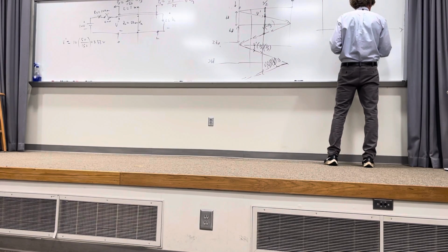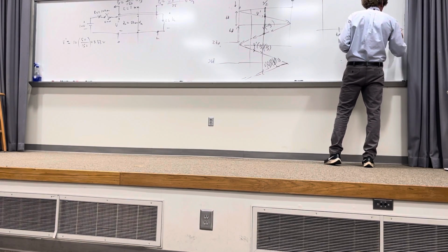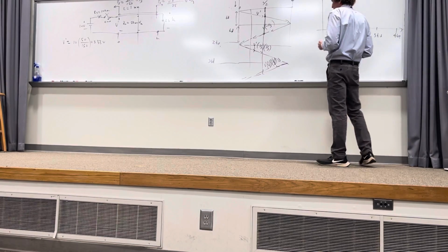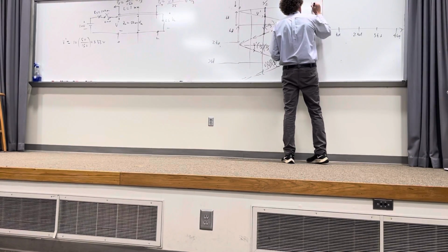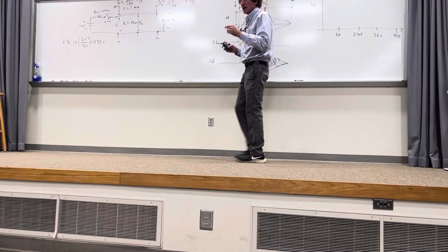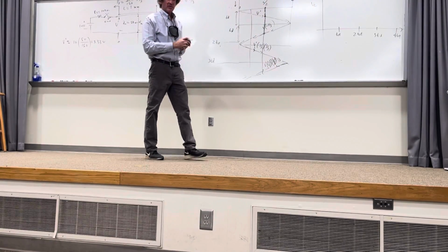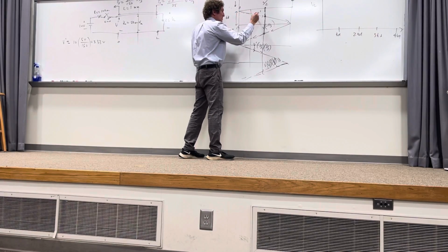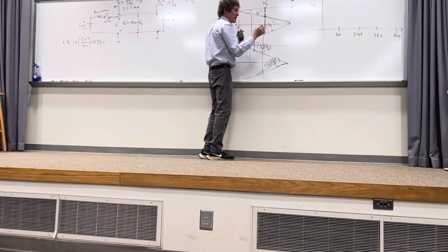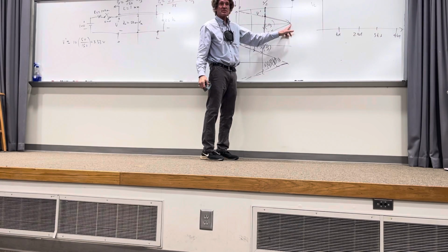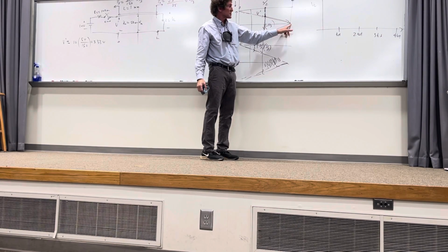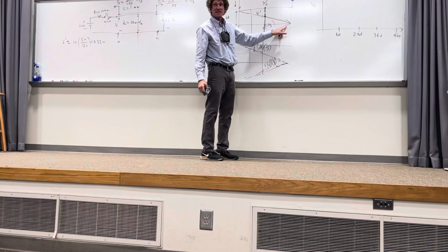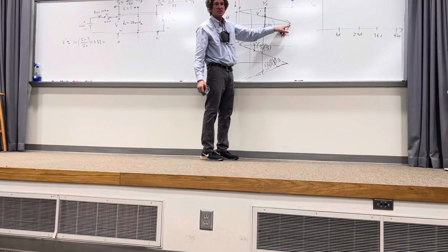Because there's a common mistake here. This is going to be voltage at the load. Now, I bet you could figure it out, but just listen to me. It's going to go down, V prime's going down, it hits the load, right? But look, simultaneously when it hits the load, there's a reflected pulse that occurs instantly. That means you have to add the reflected and the incident pulse together there. Do y'all hear me on that?